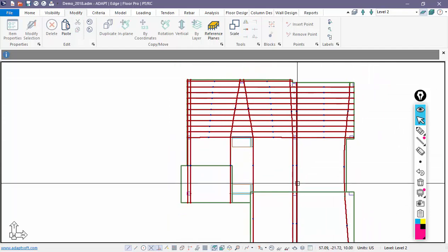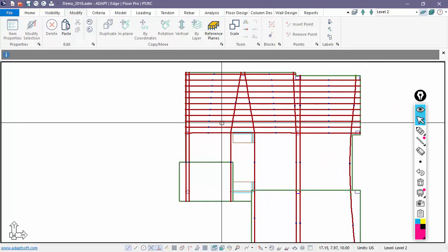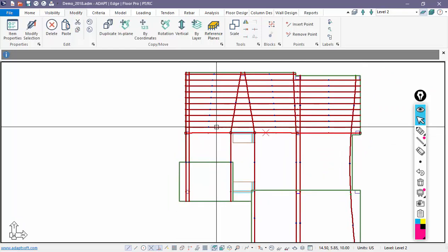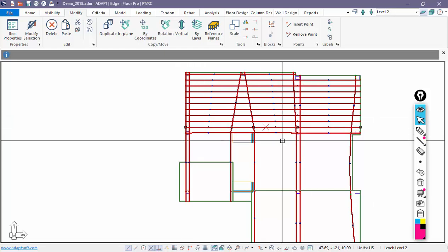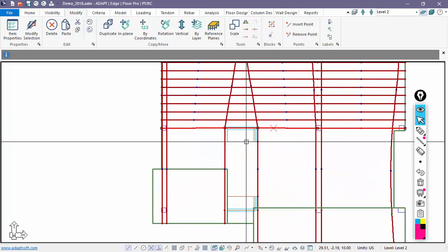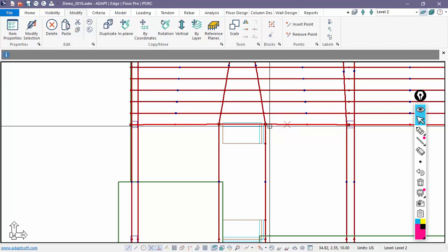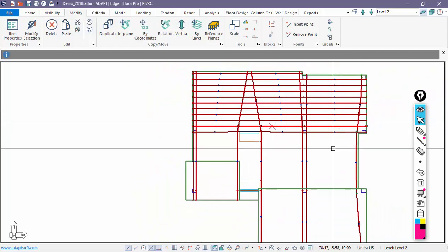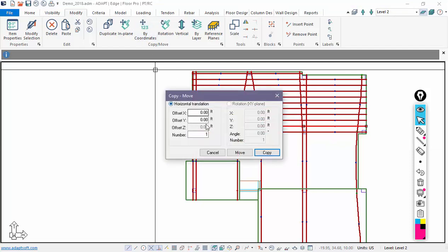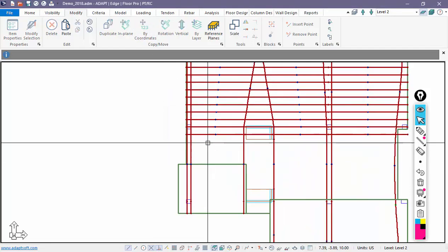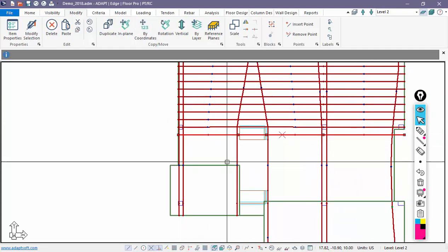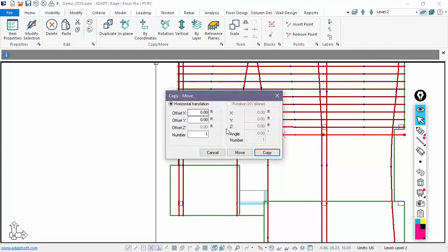We're going to do the same thing now for the second bay. What I'm going to do is actually copy this tendon. This one's aligned perfectly orthogonal. This one I moved up to the midpoint of the wall, so there's a little bit of skew to that one. Select this tendon and copy it down negative 6 feet.